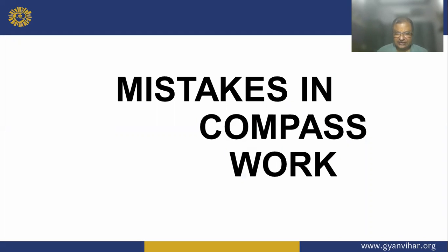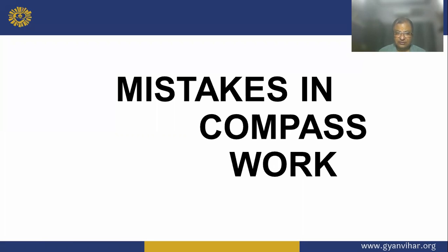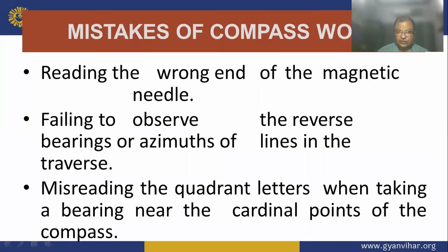Now mistakes in compass work. Reading the wrong end of the magnetic needle. Failing to observe the reverse bearing or azimuth of a line in the traverse.